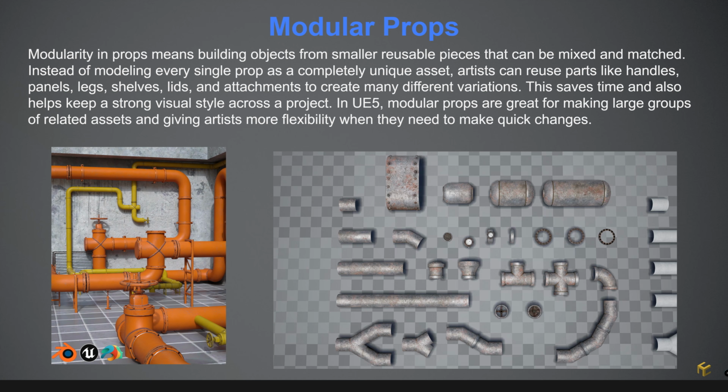Whereas if you built them into smaller pieces modularly like this, guess what? You don't have to go into Maya or Max or whatever DCC you're using. You can just take all the modular pieces that you've made and refit them again inside of Unreal Engine. This way it's still non-destructive, it's reusable, and it's a lot faster to make iterations.